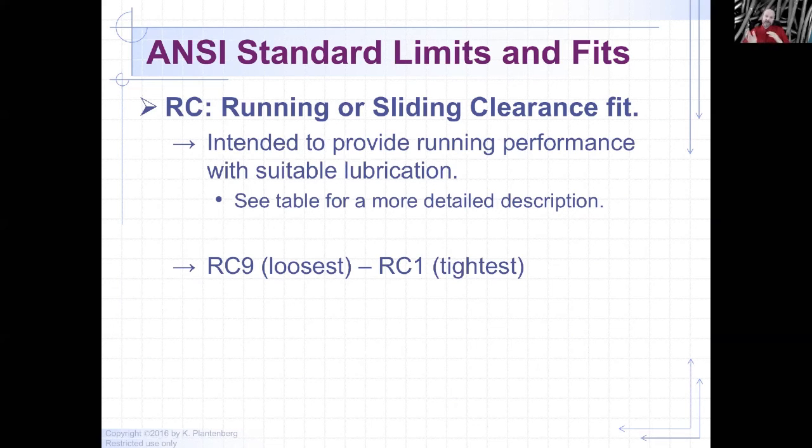Now you can start to transition over into things called running or sliding clearance fits. Okay, and that's a specification. Always think of the shaft and hole example, right? You've got running or sliding clearance, and that's intended to provide running performance with suitable lubrication, right?